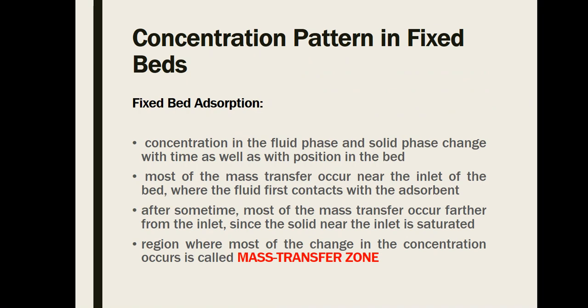Of course, in view of some of the components of our fluid being adsorbed on the surface of the adsorbent, the concentration of the adsorbent and at the same time the fluid phase that contains the solute is going to change with respect to time and with respect to position inside the fixed bed. Now, most of the mass transfer occurs near the inlet.